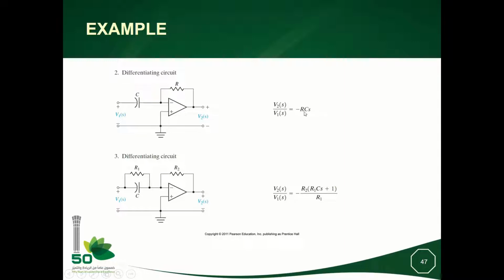So we can choose RC such that the product RC equals 1. So this circuit will describe, in the end, a differentiator with inverting action, which is minus.